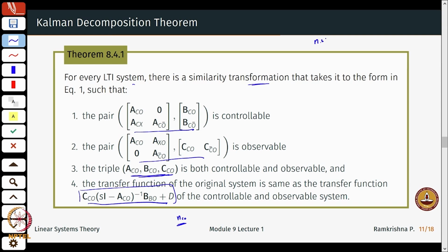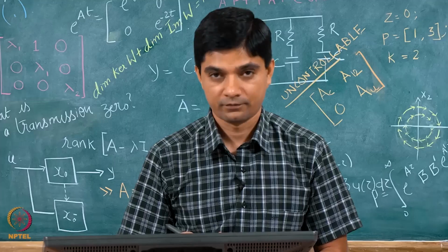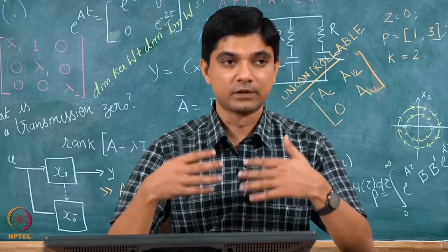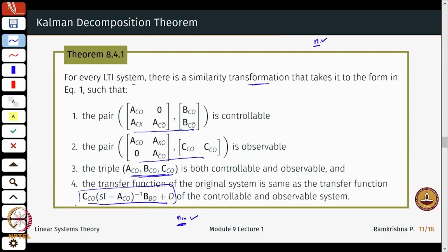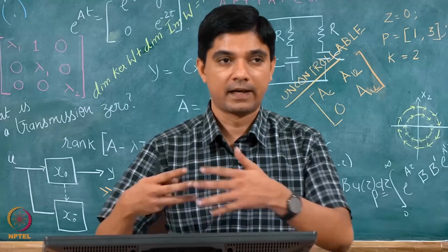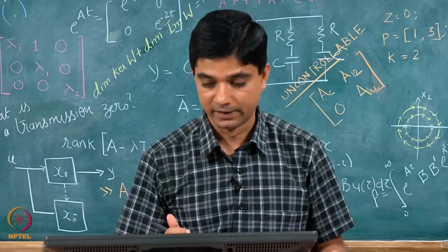Well, this is also a state space representation of the system, and I can go back from this transformation and still derive a state space representation of the system, and both are the same, right. Even though here you define n states, here you will define only n c o states. Okay. Now, we will see how to actually get to a system which only shows me the controllable and the observable form and just discards the remaining parts.